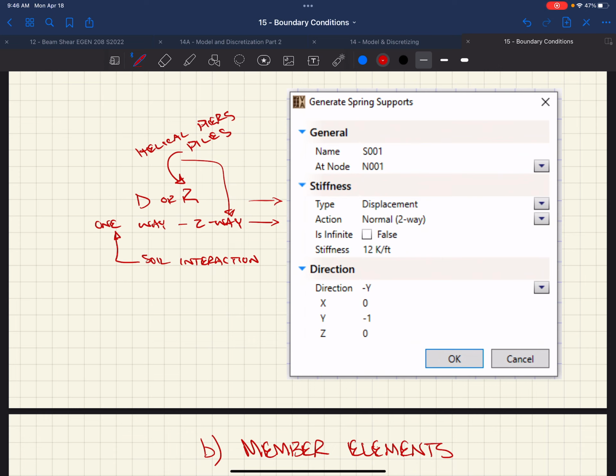So, if you could be conservative about, all right, I'm going to cantilever it maybe the first 2 feet below the footing, and say that that first part of soil isn't going to do anything for me, and then I'm going to look at just the strength of the helical pier, that would make me personally feel better about it, and if you were okay, then maybe you'd say, all right, I'm not going to batter any piles. But to batter a helical pier is really not that hard.